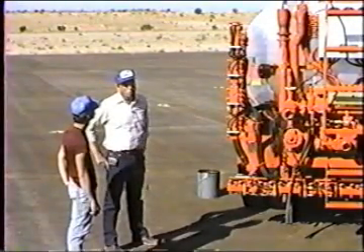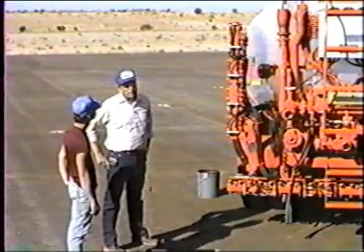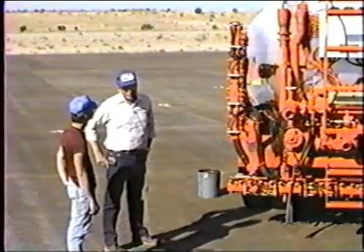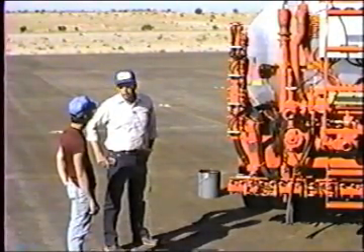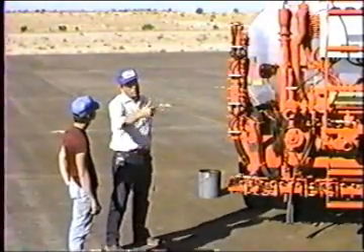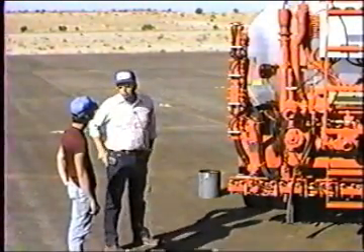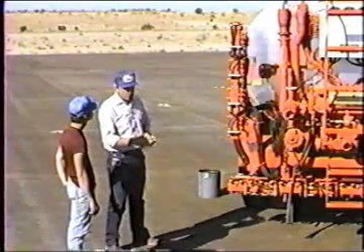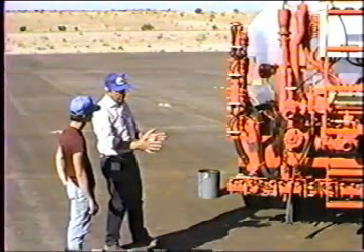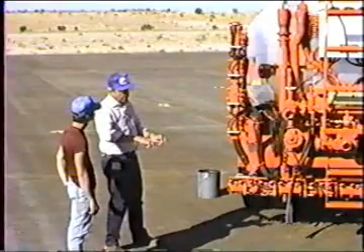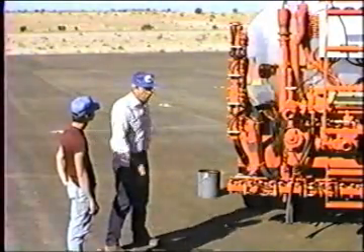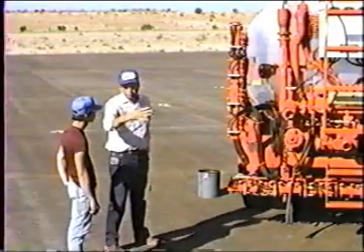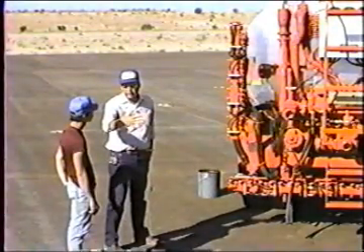That is, when you go on a state chip sealing job in the state of Idaho, on the first morning of the job you're going to be spraying down the road, and on the side of the road there'll be a yellow van parked, and he'll have spread cotton pads, 4-inch wide, 8-inch long pads, side by side all the way across the width of where you're spraying. And you just continue on. You spray right on across those pads.